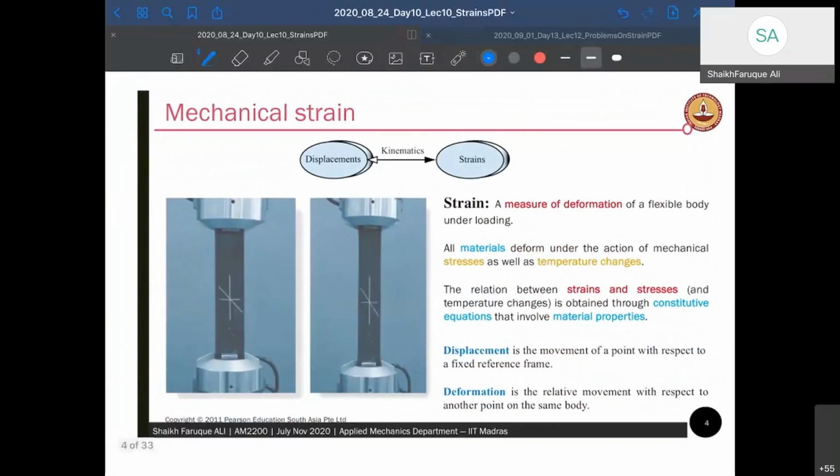Okay, so here is an example. This is how we test materials. This is a UTM body. UTM is universal testing machine. What it does is it pulls a material. This is according to ASTM standard. You are supposed to do these experiments in your second year. And you clamp them, the top and the bottom, and then you mark some lines, okay, and then you pull with some load, and you will pull till it fails, to see its yield values. We'll talk about this a little later, maybe in another week's time.